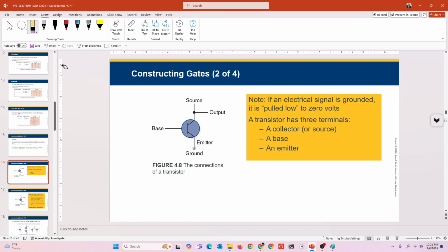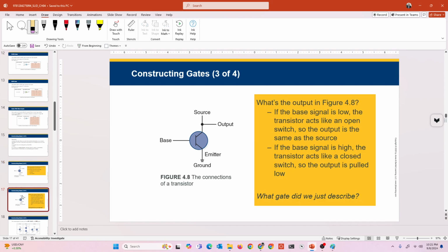Okay, let's go further. By having this capability, you can use this output as an input to another transistor, right? If you have 5 volts here, and another transistor is somewhere around here, for example, you only need 0.7 volts to excite it. 5 volts is enough to excite the next transistor, and it will pass through too. So you can use a combination of transistors and create miracles. And that's exactly what has happened in science today, because instead of talking about only two transistors, now we're talking about billions of them. Very microscopic implementations.